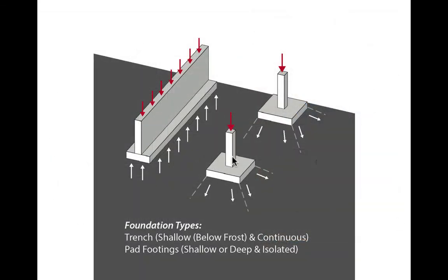We can sort of expand these spread footings to handle either columns, as we've just seen. If we sort of extrude that shape along the perimeter of the building, we get a linear spread footing. So this is what we would put underneath a bearing wall, for example. And here that bearing wall is going to act essentially like a beam, and it's going to often bridge soil that may have slightly different bearing capacity. We want that very, very large beam to be monolithic so that it can take any of that differential settlement that might happen otherwise.